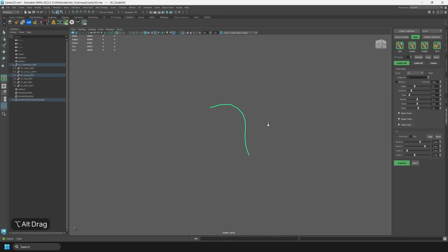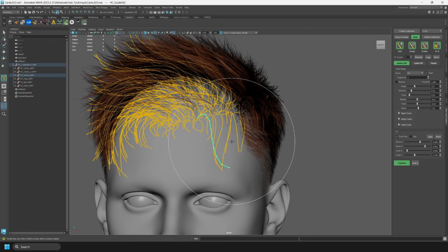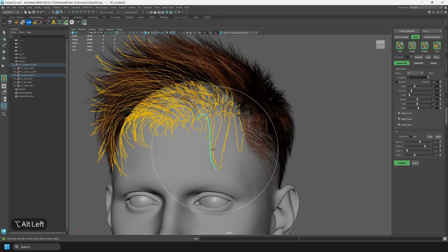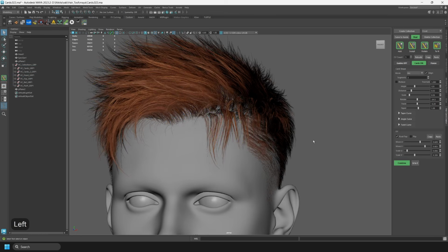Sculpt has several working modes. A normal drag edits the shape. With Control, you can lengthen the guide, the length increases, but the CVs are distributed evenly along it. With Shift, Smooth is enabled, which helps soften sharp bends. So these are the main hotkeys for sculpting: drag for shape, Control for changing length, and Shift for smoothing.